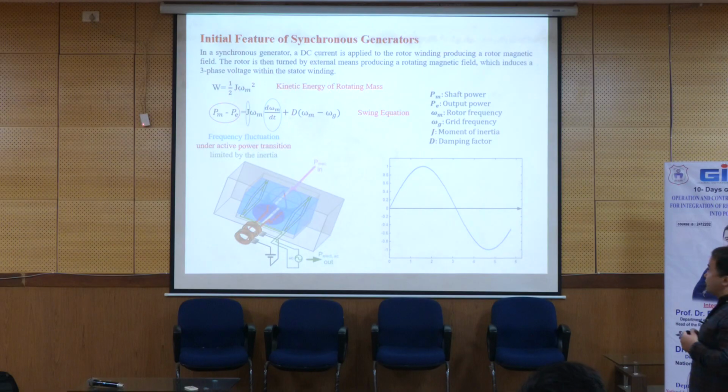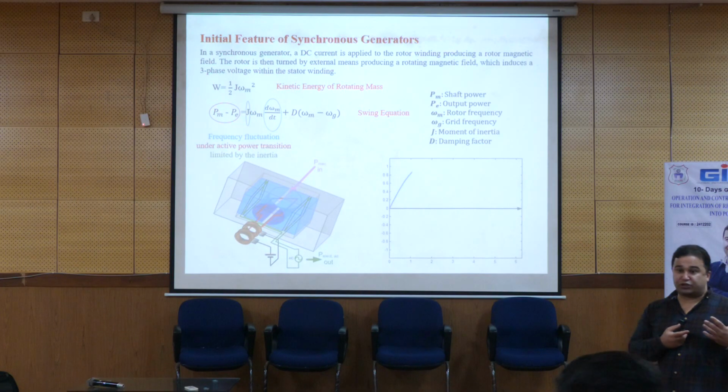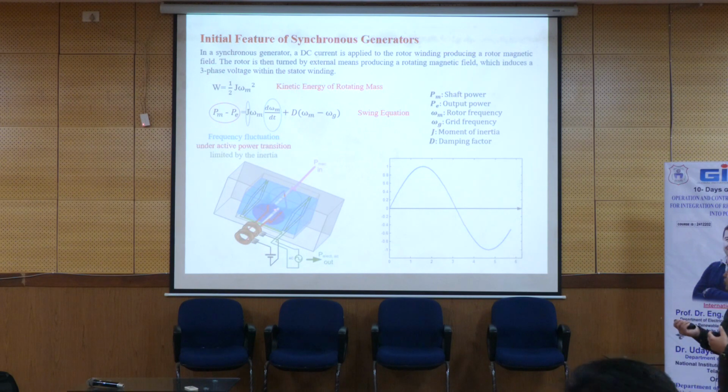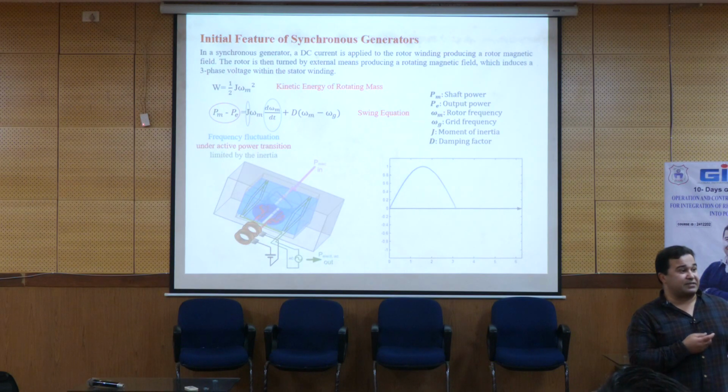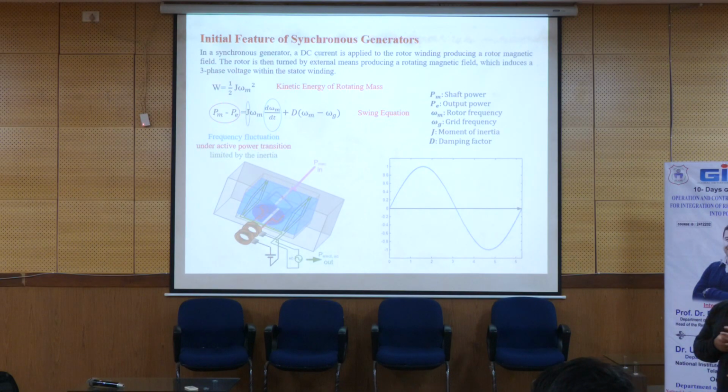So they are quite good and strong, but they are not feasible to be used for the renewable energy sources. But the solution for that is to use a technology based on the power converter, and also apply the behavior of the synchronous generator in the control of the power converter. So for this, it could be a converter-based synchronous generator, or we call it VSG, virtual synchronous generator. It means that we use the converter, but control it based on the synchronous generator model.